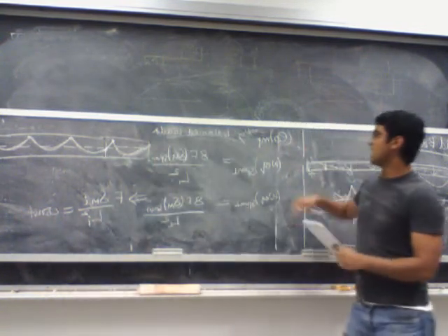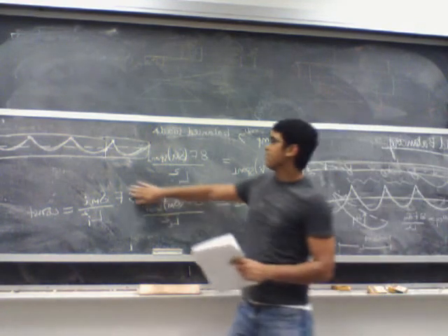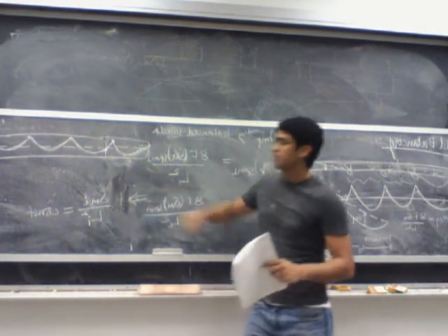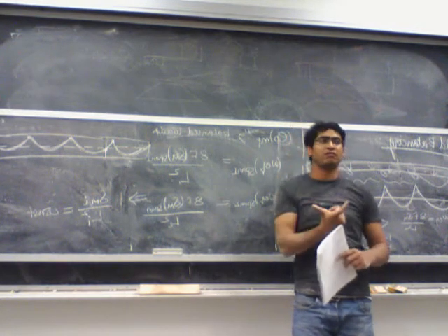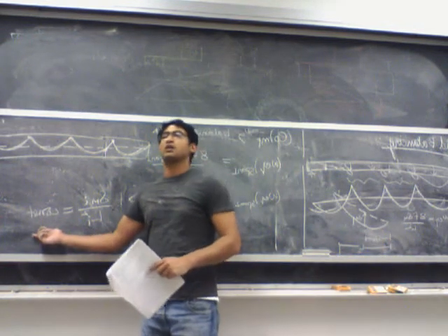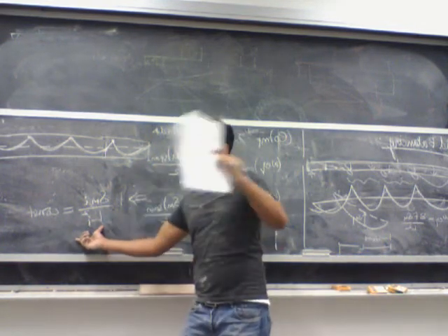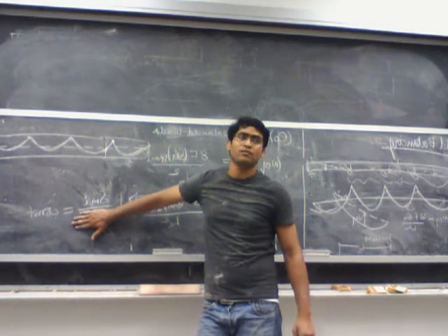Because for each one I have the same equivalent load. Since F is also the same for each span, that means my delta M for a span divided by the length of the span square has to be a constant value. If your span length is also constant for each span, that means delta M has to be constant for each of the spans, right?